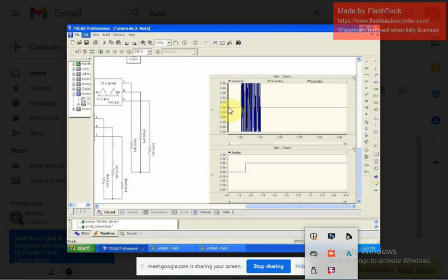Your question is, sir, this is not a pure sinusoidal wave. That is your question, isn't it, sir? Yes, sir. Actually, it is a transient. During fault, what happens is a transient. That transient, I am using with a neural network. I am training a neural network system with that transient. So the neural network system learns what that transient represents, whether it is A phase fault, B phase fault or C phase fault.